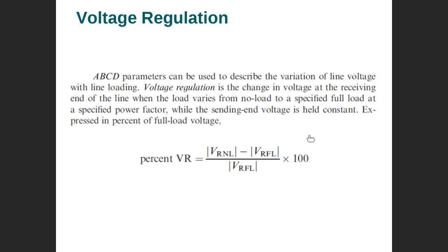So the voltage regulation will tell you how far you will go from the no load if you increase the load. So you want the voltage regulation to be within short limits, maybe plus or minus 5%. But if it is huge, then you need to take some measures there. So you need to correct things there. As an engineer, you need to correct. That's what you do, that's what you study, the system. That is in the planning section: when they do planning, you need to study the voltage regulations.